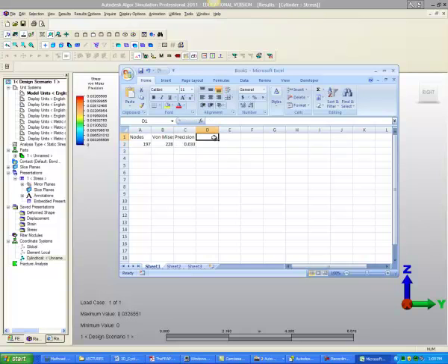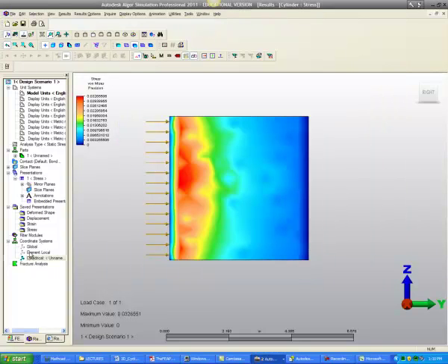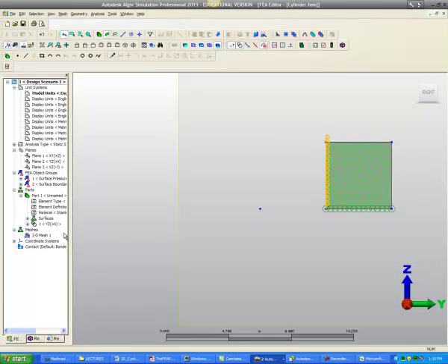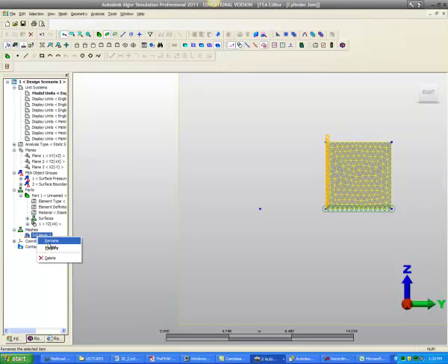Okay. And with a cylindrical problem, you'd also want to enter like the hoop stress, radial stress. But right now I just want to see if it's converging. I'm going to focus on von Mises. Okay. Now let's go back and refine the mesh. So I'm going to go back to my tab for FEA analysis. Right click on my mesh.